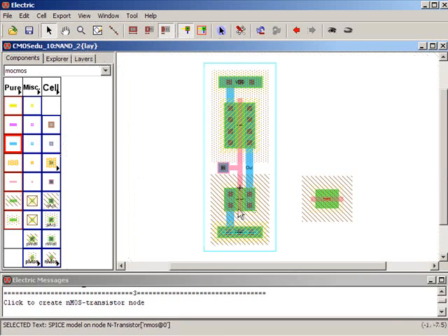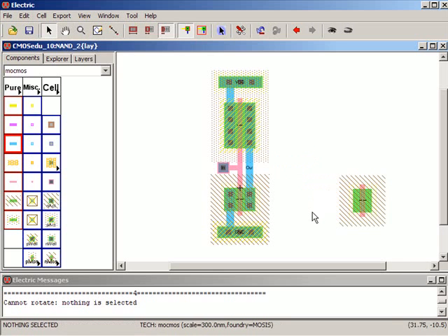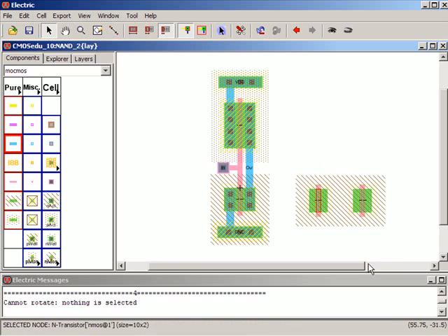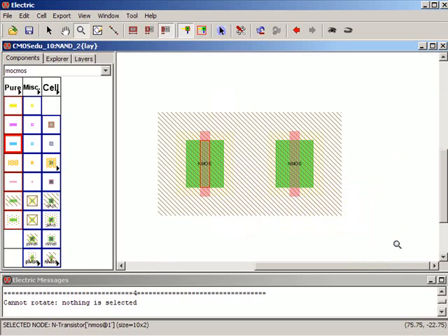And we drew this transistor with the poly going up. We could draw these with the poly, yeah, why don't we do that? So we'll go ahead and rotate, Control J. Let's rotate this node. Just see that if we pull this over, yeah, it's the same size. Since I know I need two of these, I'll just go ahead and copy this, Control C, and Control V, drop this down, fit, zoom in here.